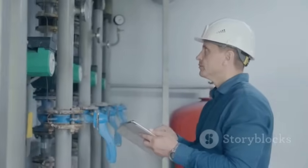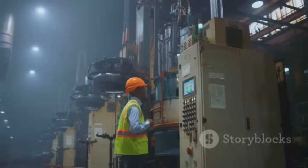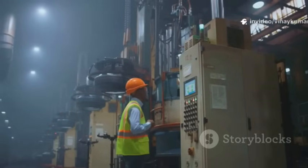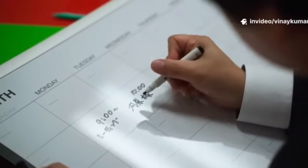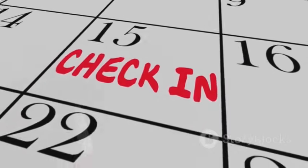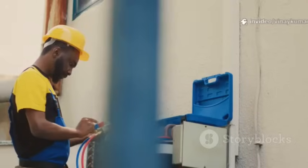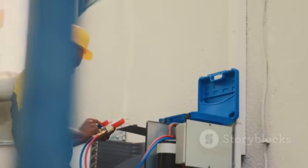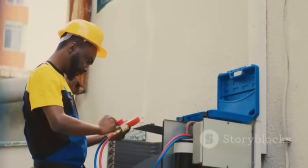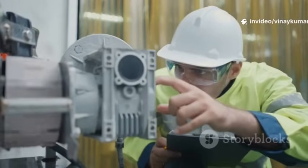A cornerstone of any good mechanical integrity program is inspection and testing. You can't just assume your equipment is okay, you have to go look. The program must include a schedule for periodic inspections and tests based on manufacturer recommendations, industry standards, and operating experience. For example, a pressure vessel might require ultrasonic thickness testing every few years to check for corrosion. A critical safety interlock might need to be functionally tested every year to ensure it works. The frequency is key. It has to be often enough to catch degradation before it leads to a failure.